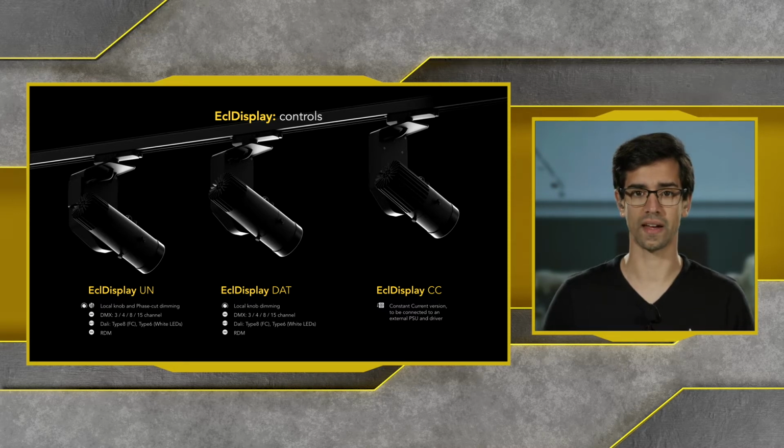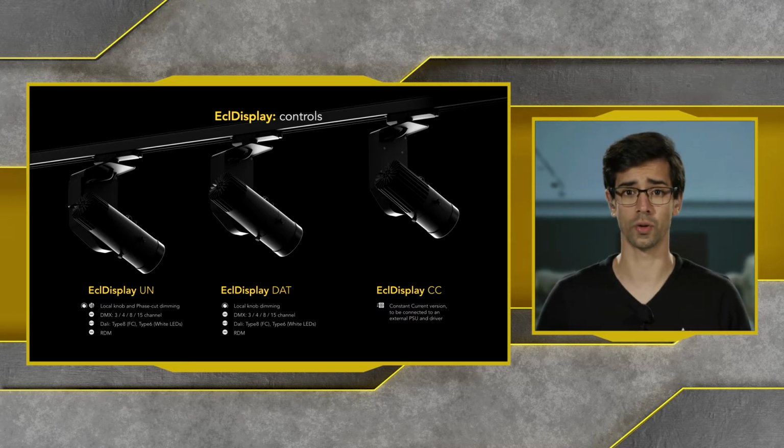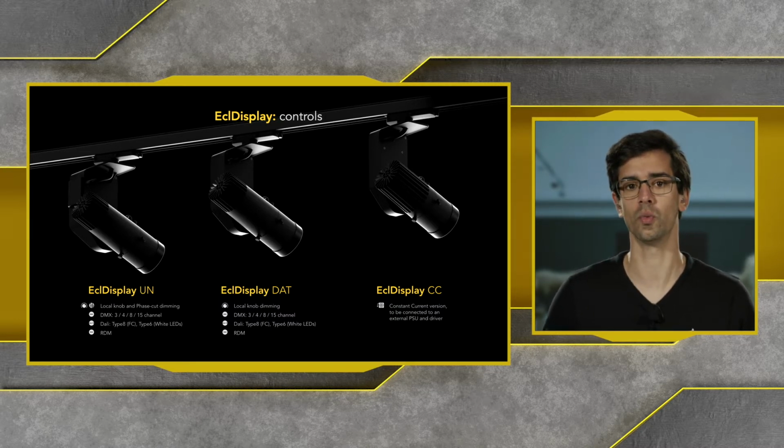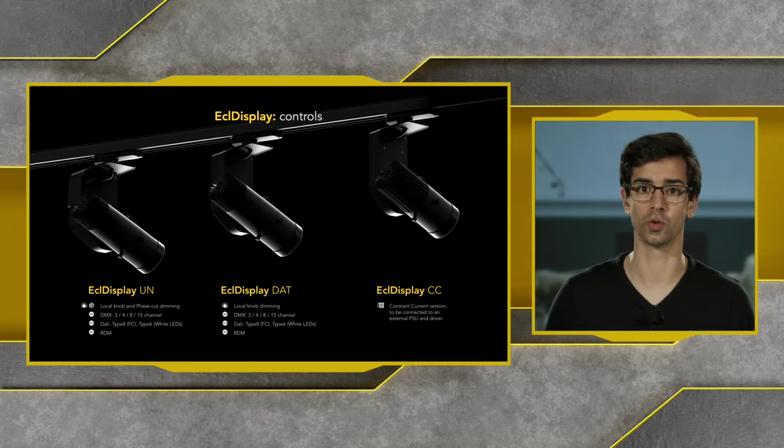In DMX, we have 4 different modes: 3-channel, 4-channel, 8-channel, or 15-channel modes. Basically, all of these modes depend on the features that you're using. There's 16-bit dimming, for example, where you can control with very fine dimming to look like an incandescent unit. And as you add more features, you add more DMX channels to control these units.